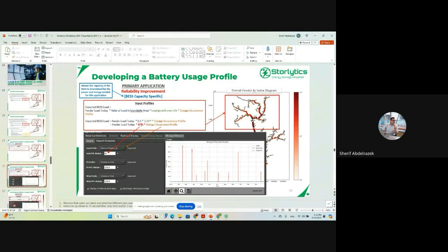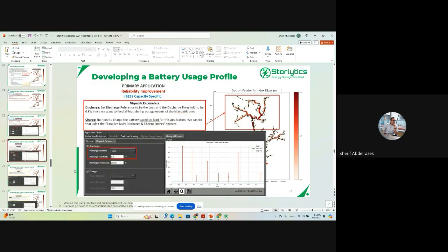So, all right, the 67% we input here is to account for the load in this region being 50% of the overall load of the feeder, and the 1.03 to the power 10 to account for 3% yearly load growth for 10 years. So that comes to 67%, and we input 67%.